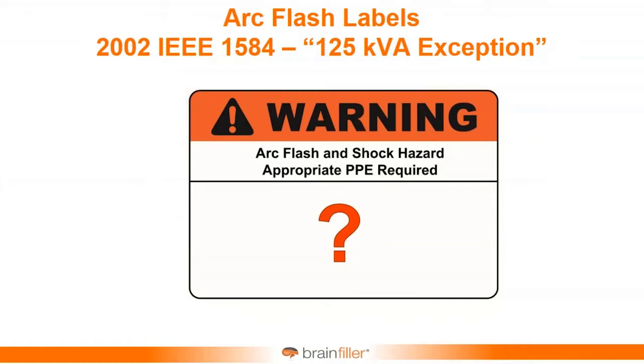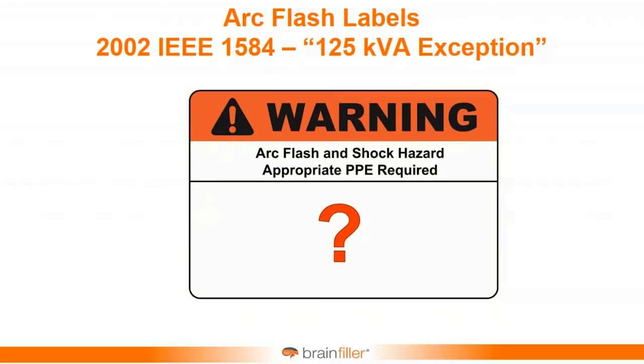I know some have said they've actually put on a label, no arc flash hazard exists. Don't do that. I actually saw that years ago from many very large organizations. The arc flash hazard is still there. It's just considered to be maybe not as significant. And some subsequent data shows that we might have been a little optimistic with that. So as I said, the new edition of 1584, you probably see a few changes.